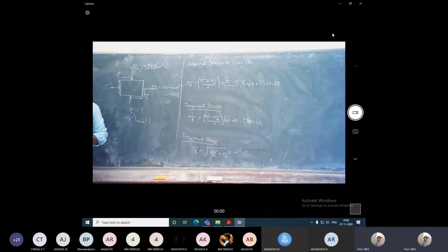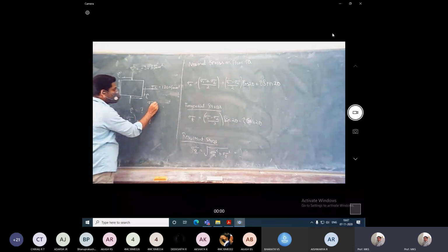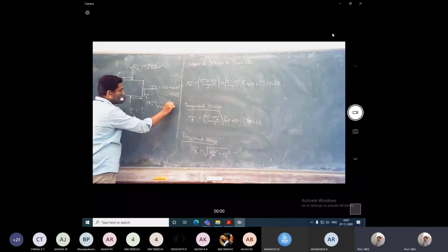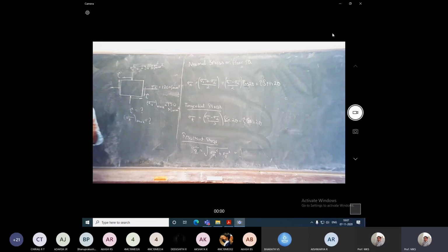So in the derivation, we found the maximum stress equation, and one more data is given. So what is that? The last sentence. The greatest principal stress at the point due to these stresses is given. The greatest principal stress, that is sigma n or sigma 1, we have derived as sigma 1 maximum. It is given as 150 Newton per mm square. The greatest principal stress, sigma n maximum or sigma 1 maximum, both are the same. It is 150 Newton per mm square.